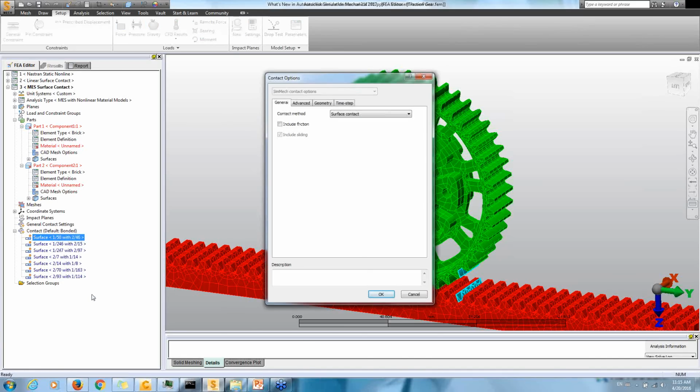That's the kind of thing where you had to click on Settings and again on Advanced and the General Surface Contact. This makes it cleaner and simpler. So you can select any surface contact pair and go to the general, whether it's surface contact or sliding or tight contact.